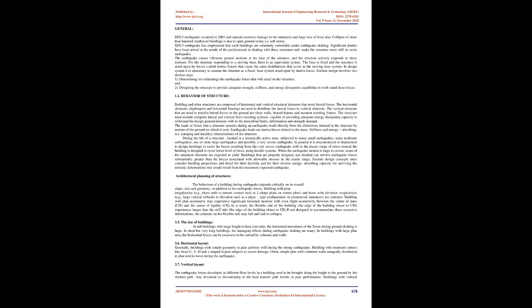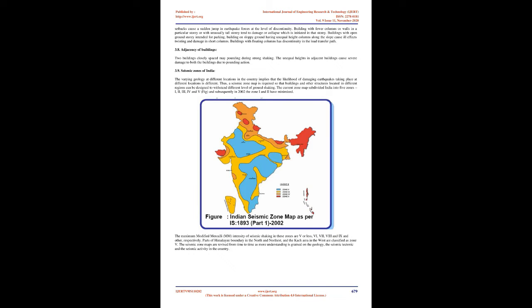8. Zone factor, Z. It is a factor to obtain design spectrum depending on the perceived maximum seismic risk characterized by maximum considered earthquake, MCE, in the zone in which the structure is located. The basic zone factors included in the standard are reasonable estimates of effective peak ground acceleration. The country is classified into 4 seismic zones as given below. Zone factor. 9. Design seismic base shear, VB.